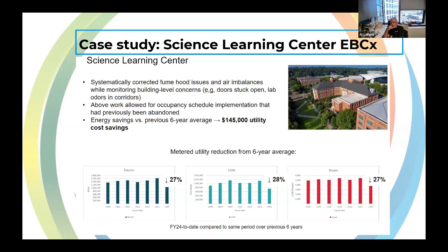Sure. So getting through that, cleaning them out, recalibrating them, our contractors helped us out on that, and then installing a building pressure sensor just to make sure that we were maintaining positive pressurization. It took a lot of work, but it was worth it because we were, first of all, saving airflow, and then also able to put on a schedule for evening and weekends.